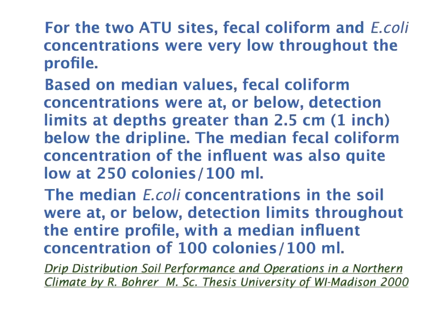This is an extract from Rachel Bora's dissertation. She took 2 ATU sites. The fecal coliform and E. coli concentrations were very low throughout the profile. Based on median values, fecal coliform concentrations were at or below detection limits at a depth greater than 2.5 centimeters below the drip line. So 1 inch below the drip line, the fecal coliform content was down to background level or undetectable. Now, the fecal coliform concentration of the influent was pretty low to start with, at 250 colonies per 100 milliliters.